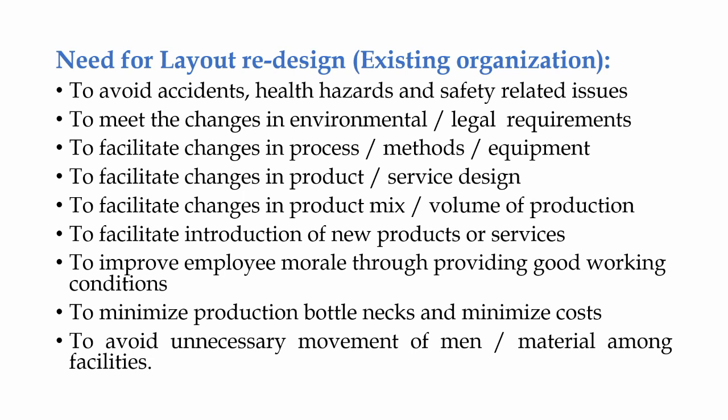Then to facilitate introduction of new products or services. Suppose we already have a few production lines which are producing different types of products. Now we want to introduce another product using the same facilities or within the same plant. In such a case also, depending on the new product's design or the manufacturing process, we may have to add some other machines or equipment, and accordingly we may have to make some changes in the existing design. In such a case also there is a need for redesigning the layout.